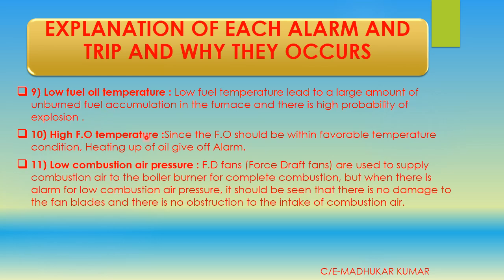High fuel oil temperature: since the fuel oil should be within the favorable temperature conditions, heating up of the oil gives off an alarm. Excessive temperature will also cause vapor locking and other associated problems.